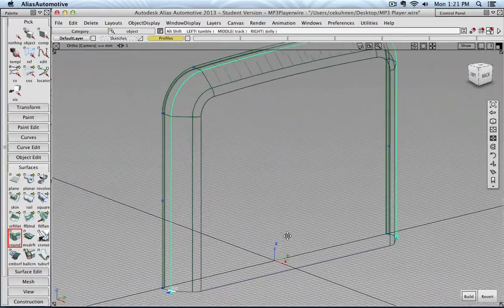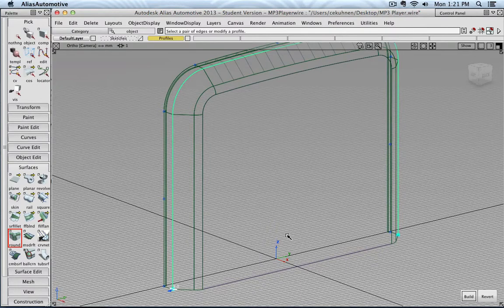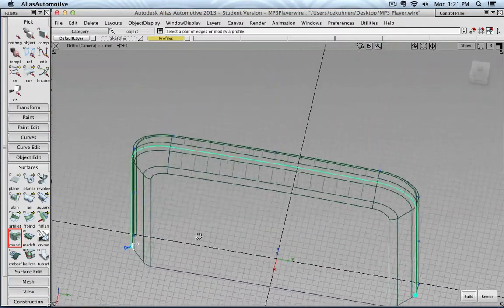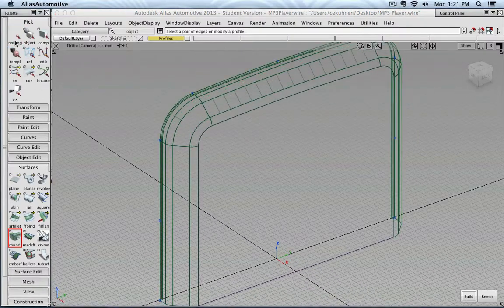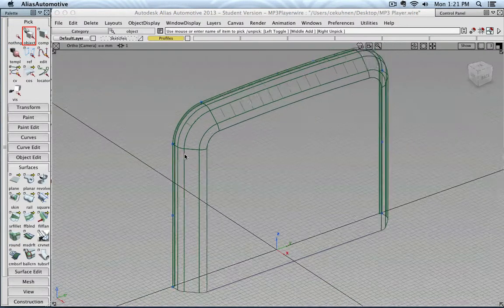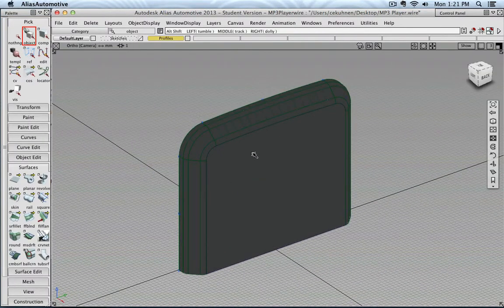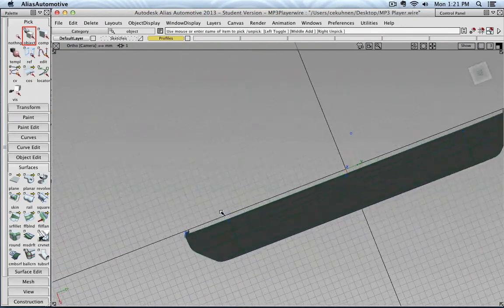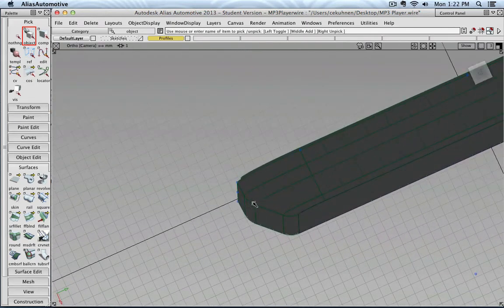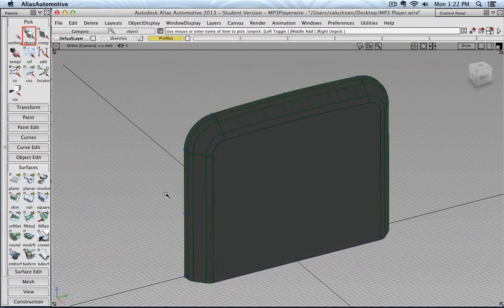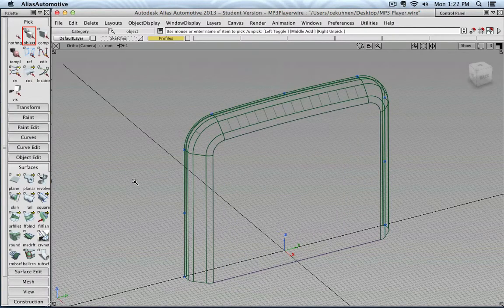And then when you have everything created correctly, so a value of 2, you can click build, and then the surface fillet is basically created for you. And let's click on nothing in object, so we leave the round command, and turn on the hardware shade. And there you can see now that we have a second fillet created here. And that's the way how you use the round command for creating the fillets.